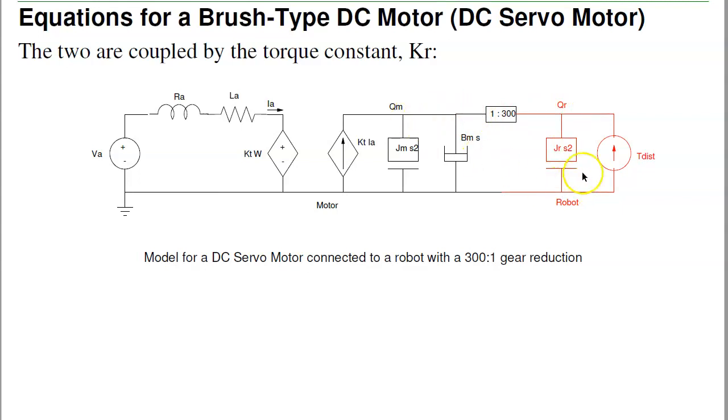In addition, it makes the outside world almost irrelevant relative to the motor. So when you have gearing, all I really need to do is control the position of the motor, and I automatically have the position of the robot. The disadvantage of the gearing is that the outside world doesn't affect the motor. Essentially, the motor is dead to the outside world. It doesn't know, it doesn't care what's out there, it's just going to blaze through it. So you have a robot with basically no touch. But it does simplify things quite a bit.